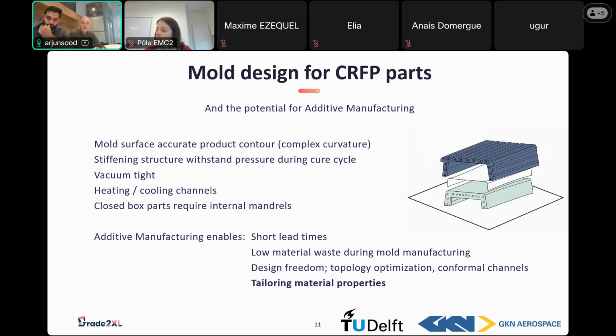A very big advantage that we see on our INVAR tooling using AM is the short lead times that we get. For big sizes we are facing lead times sometimes from 6 to 12 months for big plates that need to be specially made for our purpose. Wire arc additive manufacturing only uses wire, which is readily available.